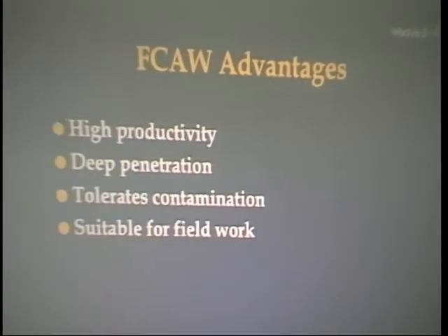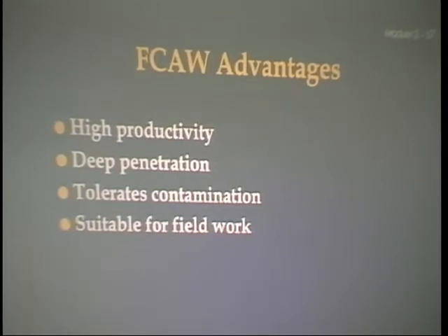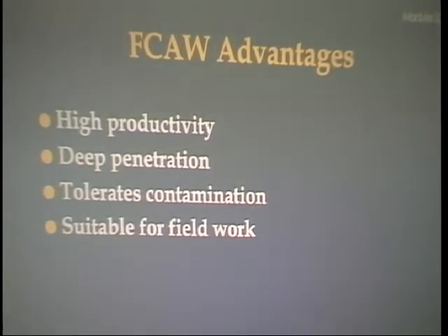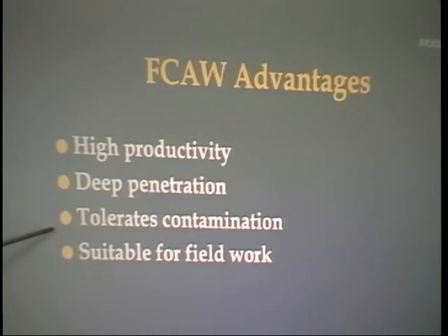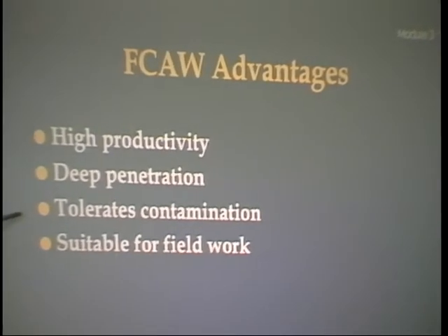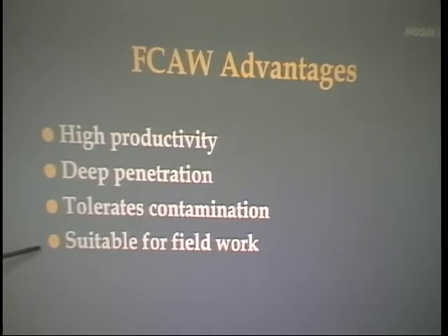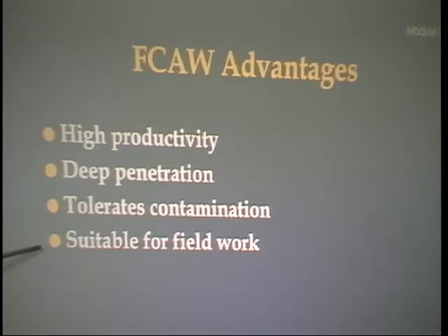Okay, the advantages, write this off in the side of your text someplace. Advantages of Flux-Core arc welding: high productivity, deep penetration, tolerates contamination because it produces so much energy, it'll burn most of that crap out of there. Suitable for field work. So write those down.